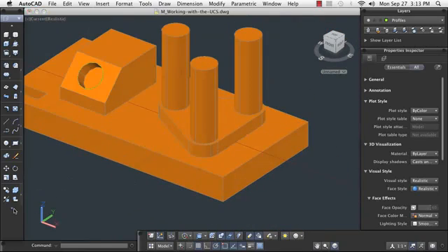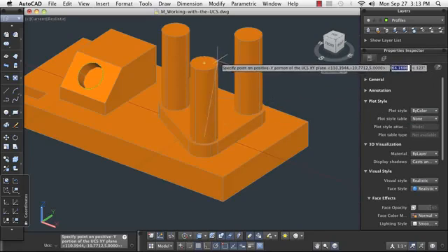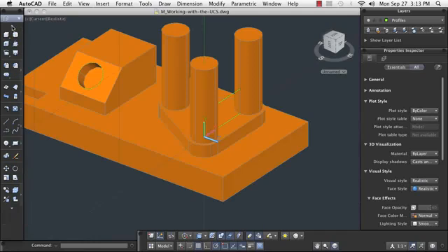When a point and surface are not available or convenient, the UCS can be oriented by specifying a new origin and calling out specific points to determine the direction of the X, Y, and Z axes. Here, since I want a rib to run between the two cylinders, I will use the features on the cylinder to reorient my UCS. This process is much easier than drawing or modeling an object in one plane and then trying to move and rotate my object to get it aligned correctly at another location on my drawing.